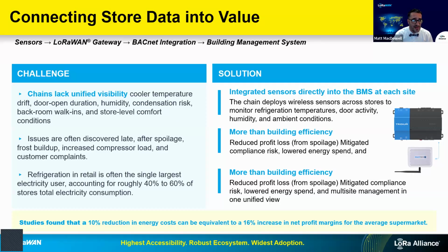So by deploying integrated sensors directly within their BMS system at each site, they not only leveraged their existing administrative portal for their BACnet building automation system, the BMS, but now they can add additional sensors in a scalable way. We can start with one or two for temperature and humidity, and then door open, door close sensors. When you bring all that data into one unified platform, like Moab was explaining, with the AI being that physical layer, you start to really break down the silos and you can tell more complete stories.